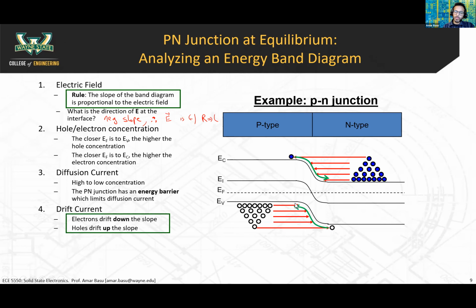Now, again, I'm going to rehash why that is. An electron on the p side sees a slightly lower energy state right next to it. So the electron takes that lower energy state, and then it finds an even lower energy state right next to that, and then an even lower one after that. So it basically finds energy states and just continues on this way.